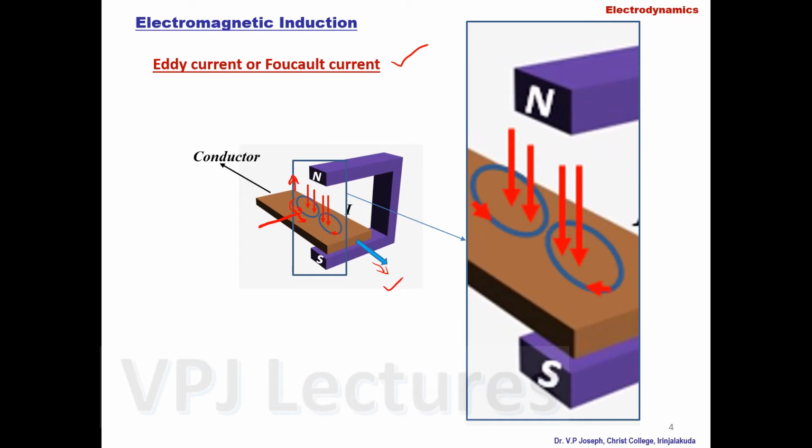So that generates a magnetic field in the upward direction, or based on Lenz's principle, the growth of the current in the circuit is opposed. And at the time of exit, corresponding to this region, the conductor is trying to move away from the magnetic field. The current produced inside is in the same direction as that of the external magnetic field, so the current will be in the clockwise direction, like this.